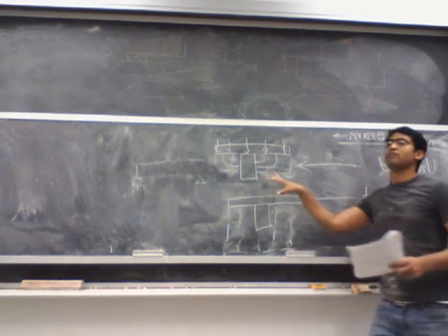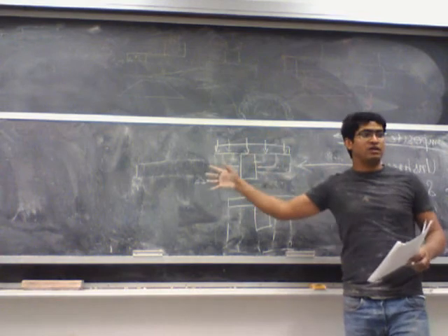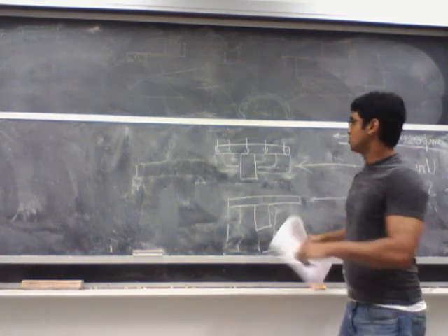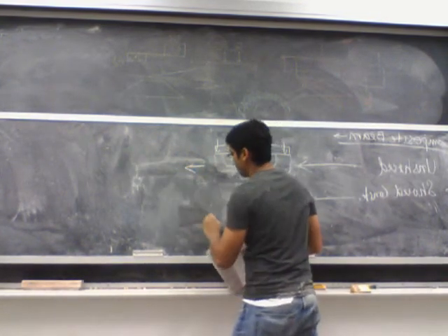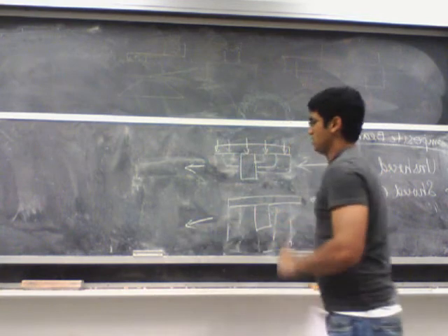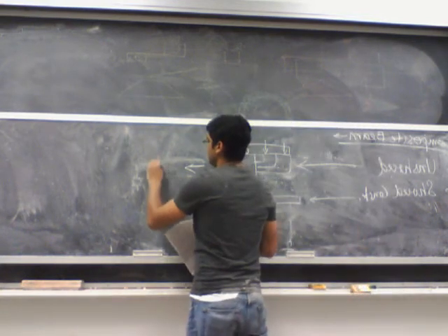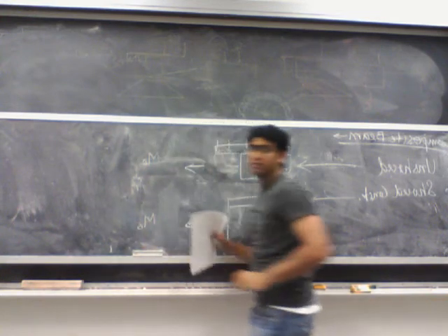Once you have this composite section, you have the dead load, live load, and all the service loads applied on this beam, right? If you look at the method of loading in the two cases, the first thing is simply the self weight of the girder.